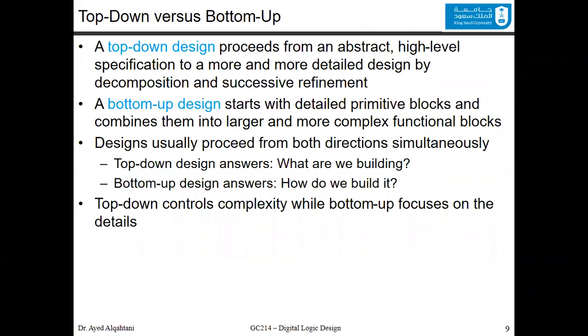So from what we've introduced so far, we actually have 2 ways to design any logic circuit. We have a top-down design, or a top-down approach, that proceeds from an abstract high-level specification to a more and more detailed design by decomposition and successive refinement. The other way around, we have a bottom-up design that starts with detailed primitive blocks and combines them into larger and more complex functional blocks.